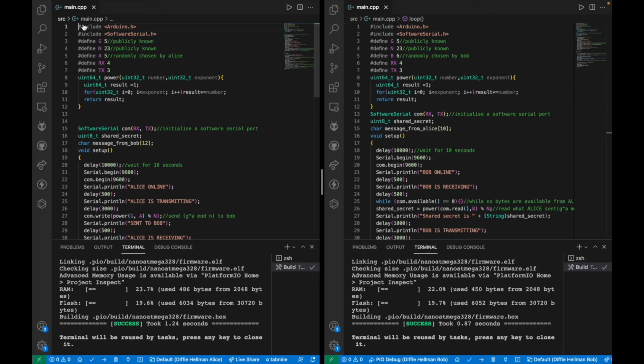So first, in PlatformIO, you have to include this header file arduino.h to use the Arduino libraries and functions that the Arduino framework provides. In the Arduino IDE, this happens automatically. So in the Arduino IDE, you may delete this line, but even if you don't, things won't change. It will be included automatically. Next, we include the SoftwareSerial library because we will be using a software serial port, not the hardware serial port, for serial communication, so that we don't have to plug and unplug cables during upload.